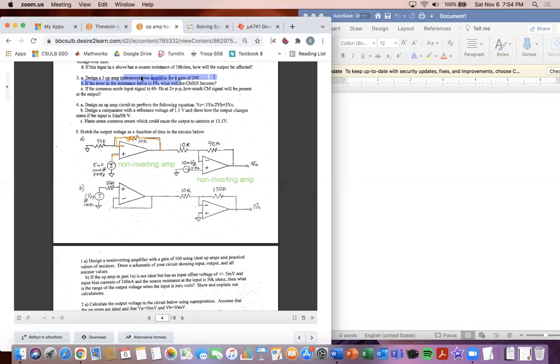So there will be a voltage here. I'm going to call it V out, and put an apostrophe here, V out', for the output voltage from the first op amp. And so if we have a voltage here also at the negative terminal, we're going to have to use superposition here. We're going to have to look at what this has on effect on the inverting amp, and then look at how the other one affects the non-inverting amp. So let's go one by one. Let's calculate the voltage output for the first amp over here. So we're going to focus on this portion over here. So let me circle it. That's what we're going to be doing.